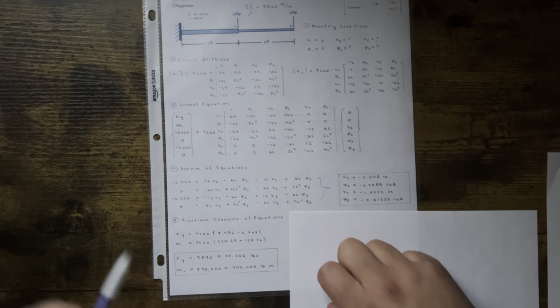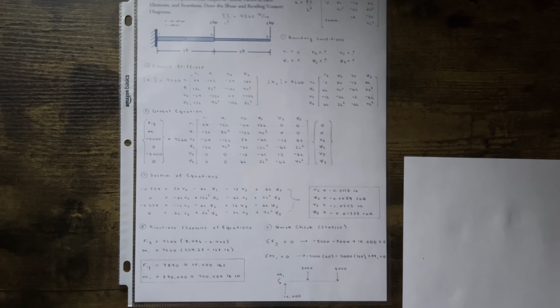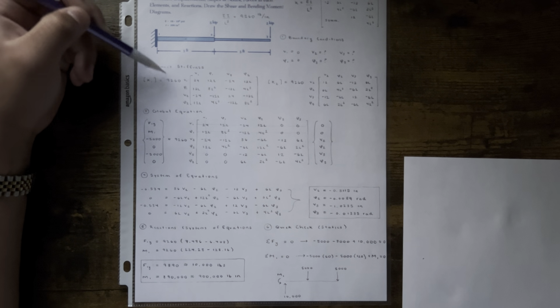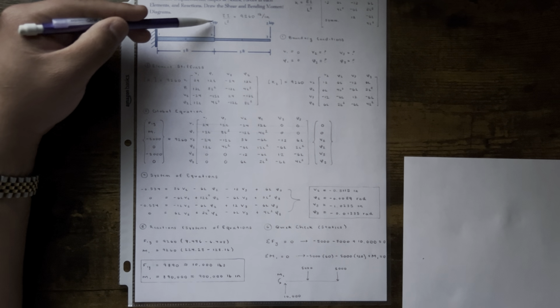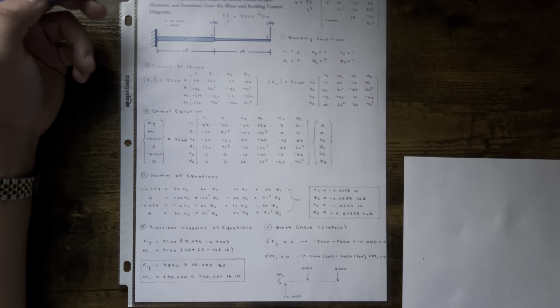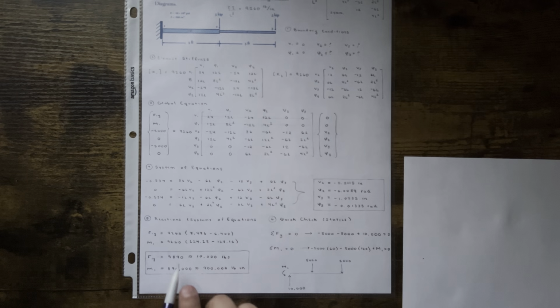And the next step after this is just verifying it. An easy way to verify it is through statics. So let me show you the answer right here. Do a quick statics check, very easy. Sum of the forces in the y direction: whatever goes down is equal to whatever's going up. So in this case, you have 2 5,000s going down, which means going up should be 10,000. F1y, I calculated to 9890, but that's just rounding error.